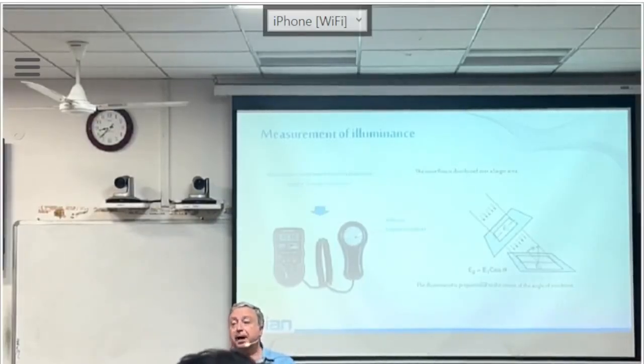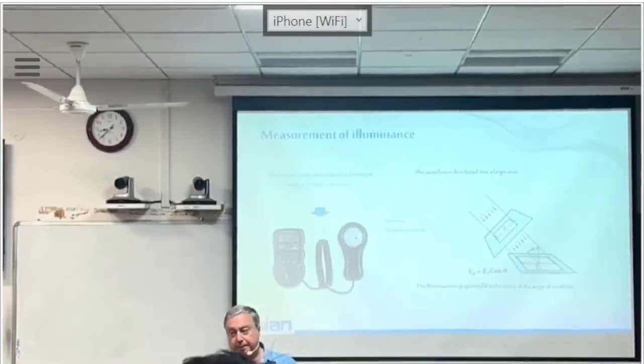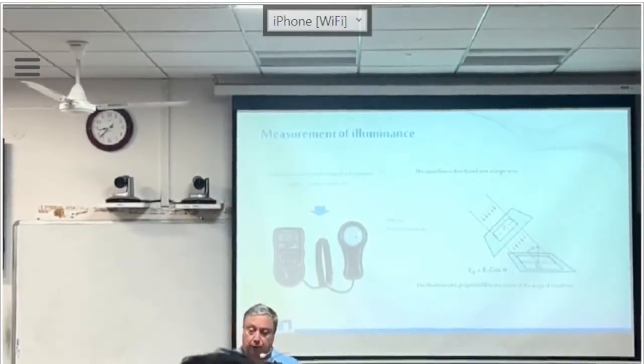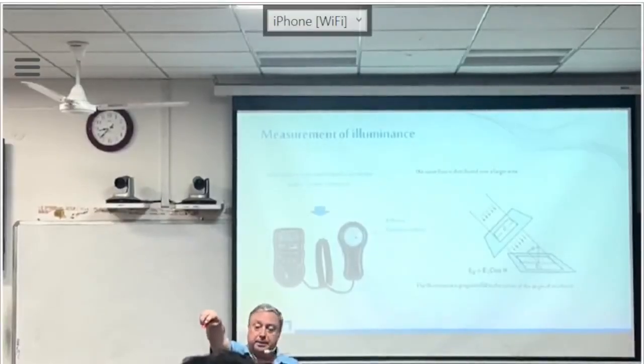The very cheap instrument, less than 500 euros, is not calibrated, because a single calibration point is globally 500 euros. And normally in a metrology lab, you have to calibrate all your instruments at least one time per year and have the calibration certificate. You understand that when you buy something for 4,000 rupees, it's not calibrated, that means you cannot measure the absolute illuminance here, but you can say here I have 2 times more illuminance than here. In relative terms, it's working okay.